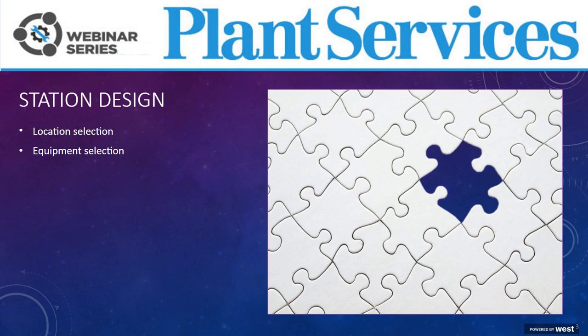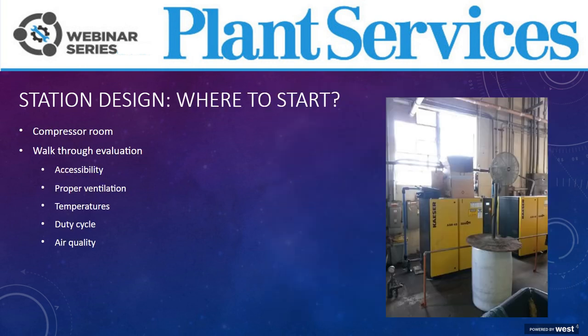What if we simply said you need so many CFM at a particular pressure with a certain air quality level? When designing a compressed air station, these are the questions we'd recommend asking yourself or the equipment vendors that require compressed air in your facility. Just because you have existing compressed air equipment, they may not be the most efficient to meet your needs. Plus, the current location may not be the most hospitable. So let's examine these items a little further.